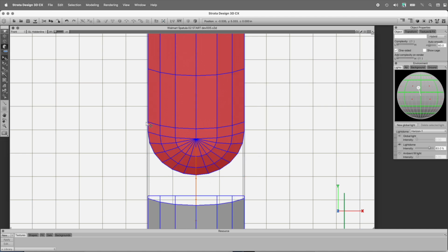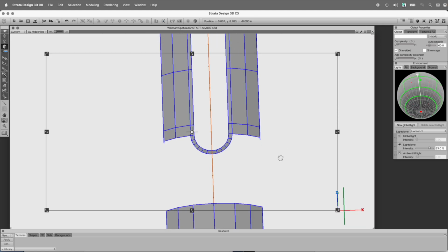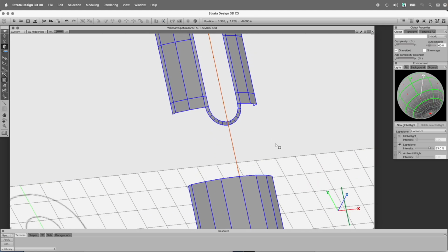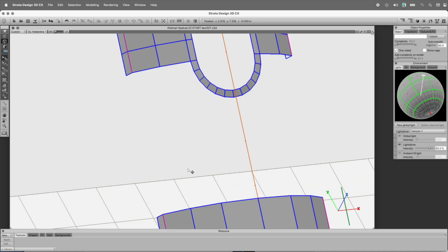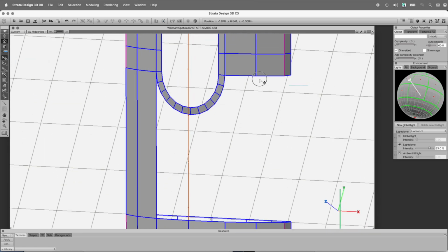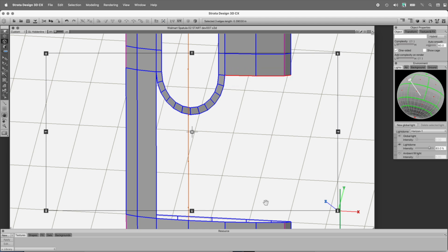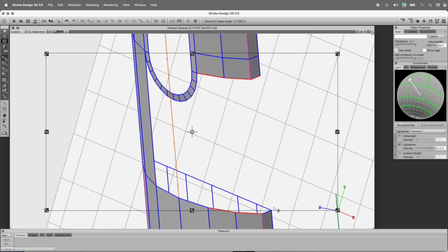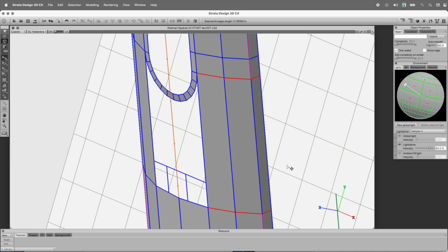Okay, so let's leave edit mode, cut that, and we need to reintegrate that back into the primary object that we're working with. So let's come over now that we've gotten that established into edge mode. We can take these edges and match them up down here to these edges. B key to bridge. Do the same thing on the other side. Grab those and B key to bridge.